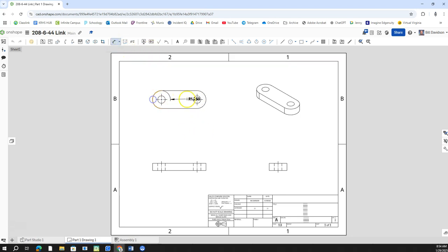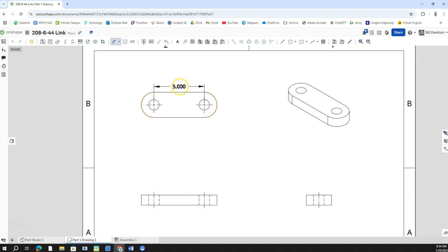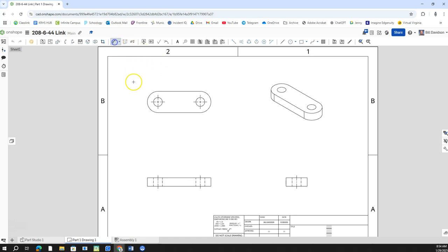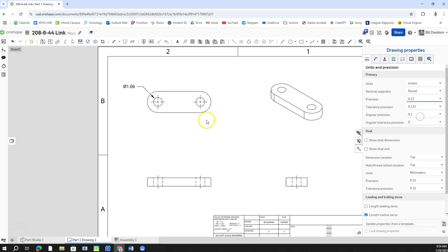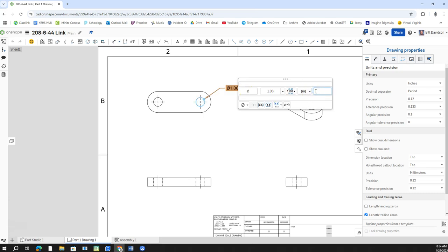I'll put dimensions on as they were in the sketch. I wonder if I can do that. So I'm going to go center line from this end point right here. Can I get to that end point right there? Well, that's not going to work for this view. So I'm going to do a dimension on this part right here, and I'm going to change this to be 2 decimal places, and I'm actually going to change this to the other side because I like the spacing of this better, because I'm going to need to do more. And when I click this, I'm going to change that to space and caps lock on TYP, and I'll change this down here to say 2 places. All right, so I got that.